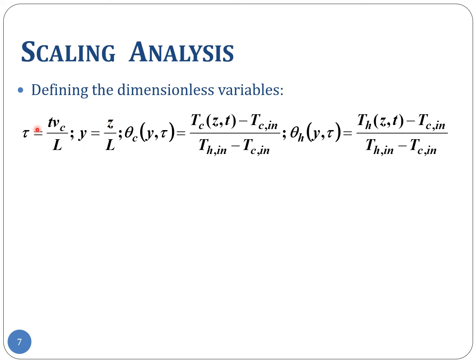Now we come to time. If you look at this double pipe heat exchanger system, even in the equation that we developed, it is apparent that there are two phenomena taking place. One is bulk convective transport of the cold fluid through the inner pipe, which is captured by the left hand side of the equation, and the second is the heat transfer into that flowing cold fluid from the hot fluid through mixed conduction, convection, advection, Newton's law of cooling.